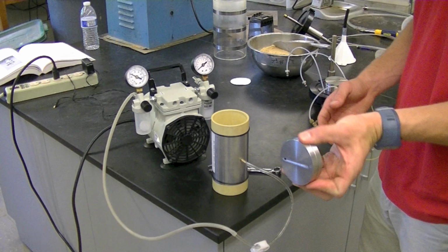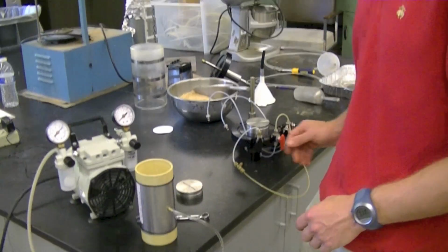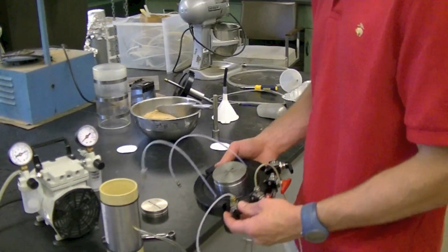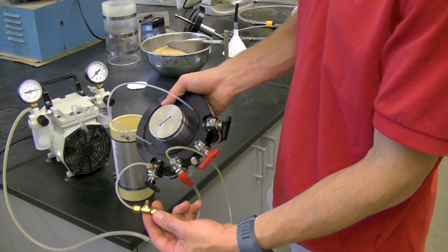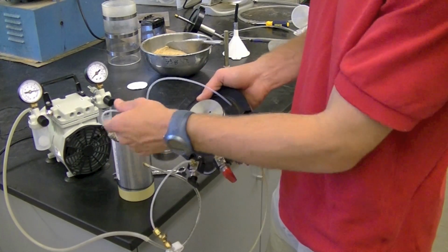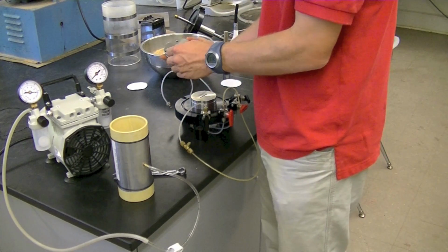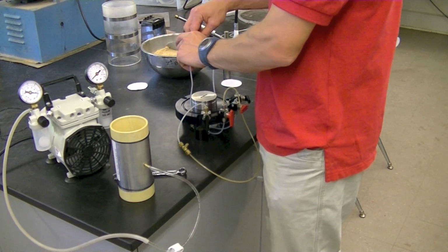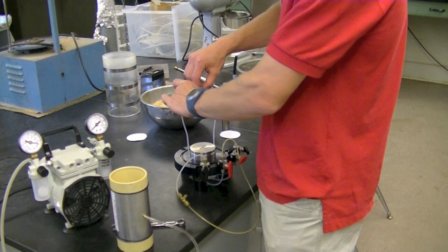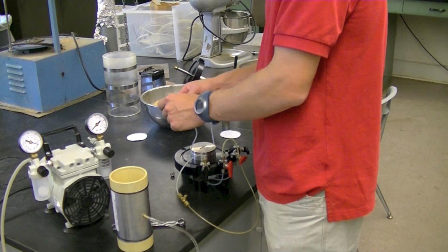The top and bottom platens are made of stainless steel or lucite and must contain flow inlets. The base pedestal contains the valves for drainage lines and pore pressures. The black and red nozzles on the left side of the base pedestal control the left top and bottom drainage lines. Notice the top and bottom are bridged for now. We will bridge the left top and bottom drainage lines during specimen molding to keep the dimensions consistent.